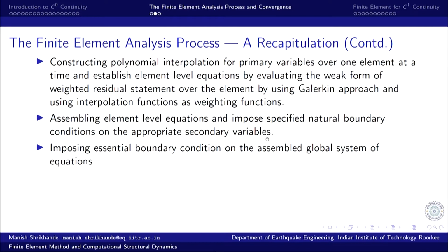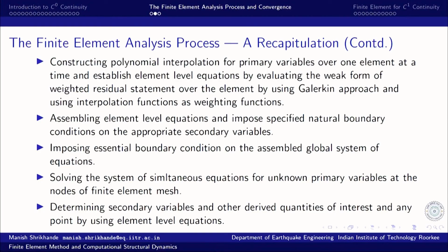after this point, after the imposition of secondary variables or natural boundary condition, and then the element level equations are transformed to global frame of reference, and then they are assembled into global system of equations before the essential boundary conditions are imposed. And after the imposition of essential boundary condition, the simultaneous equations can be solved for unknown primary variables at the nodes of finite element mesh.